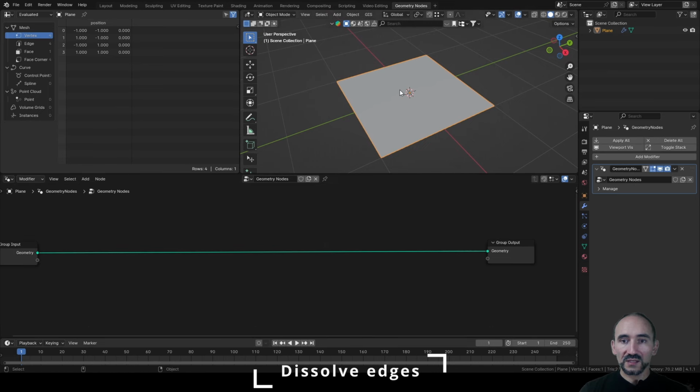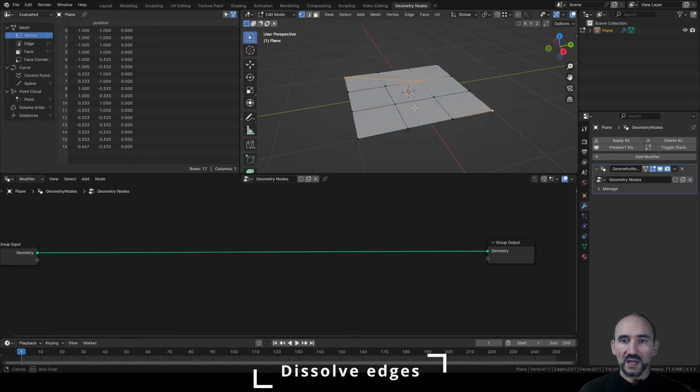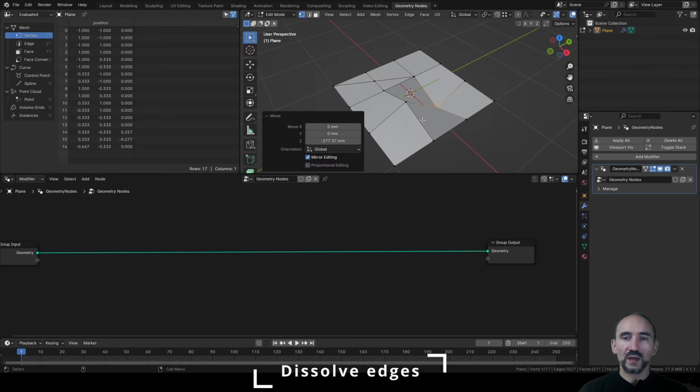So to test this idea, I enter in the edit mode, select all, right button, subdivide twice, and also I press K for the knife and trace a little line like this. Next, I'm going to take some vertices and move up a little bit or down, because what I want is to have an entire flat surface to have the correct normal of the vertices.